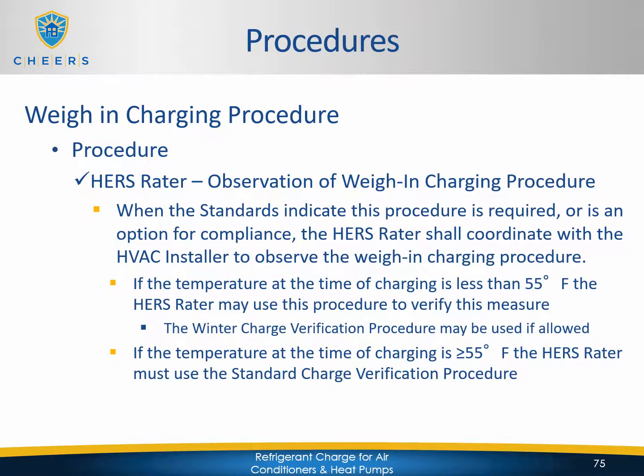Now, as the HERS rater, you do have the option to observe this weigh-in charge procedure. Again, you're not going to perform the weigh-in charge procedure, but you will observe the installing contractor weigh in the charge. You're allowed to do this when the standards indicate that the procedure is required or is an option for compliance. So you will need to coordinate with the installer to be on site and observe the weigh-in charging procedure.